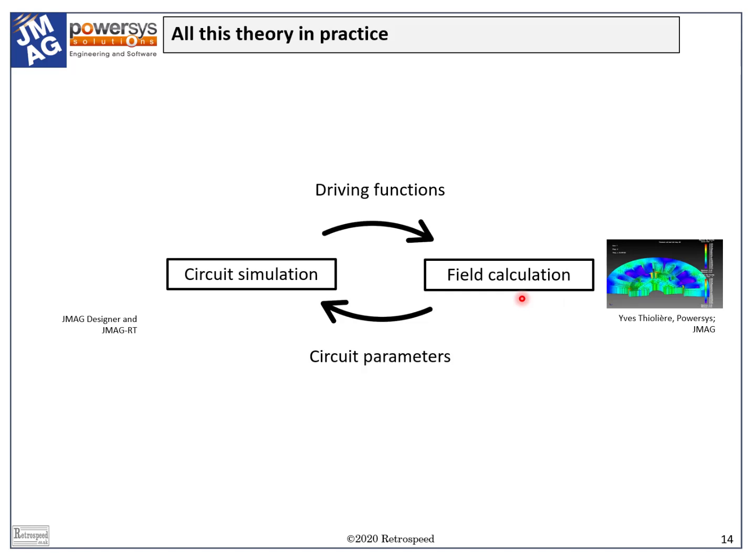What happens to all the other harmonics? Well, they produce parasitic effects, torque ripple, additional losses, and they appear as additional leakage inductance, harmonic leakage inductance, but all these effects are usually of secondary importance and do not change the fundamental control behavior of the machine. Oh yes, and I haven't even mentioned eddy currents or core losses. But all these effects are, of course, within the scope of the most advanced software tools.